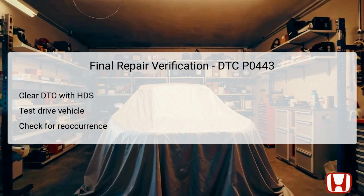Following the completion of the troubleshooting and any necessary repairs related to DTC P0443, it is vital to conduct a final repair verification. Begin by clearing the DTC using the HDS, which stands for the Honda Diagnostic System. This action resets the onboard diagnostics and allows for a fresh assessment of the system's performance.